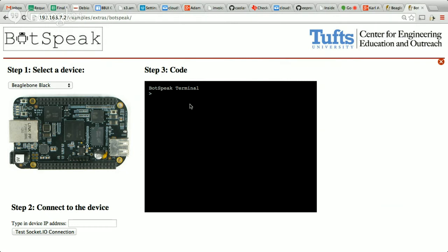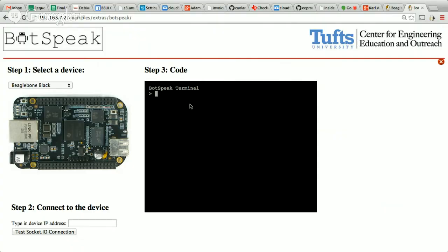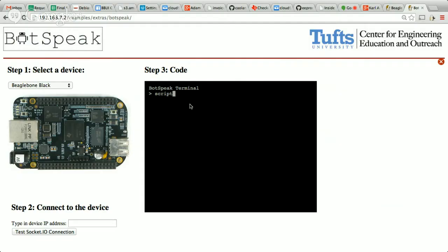But I guess the whole program would have to be downloaded to the PRU first then, because if you're just waiting for each line of code to come in before you can run it, then you're not going to get that reliable timing, right? Correct. So when you want to send a script down, you start with script and then you do, say, set BIO 0 to 0, you do wait.